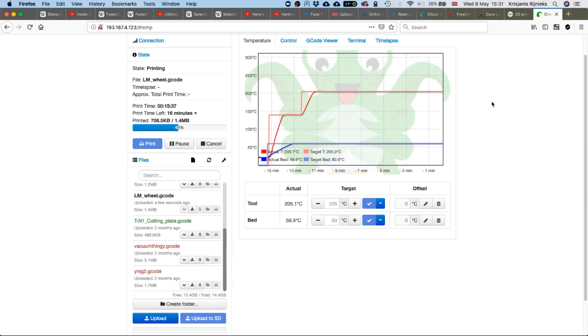Yeah, this is the benefit of this technology. If you choose the settings right, and if you just need a basic prototype, then it can be very fast. But if you go with high detail, then it might easily take up to 40 hours, like 24 to 48 hours. There have been prints that were running for 4 hours and more. And usually with these very detailed prints, it's much more likely that the nozzle of the printer is going to jam. You have to be very careful with that.